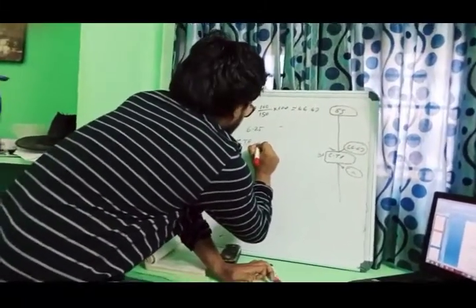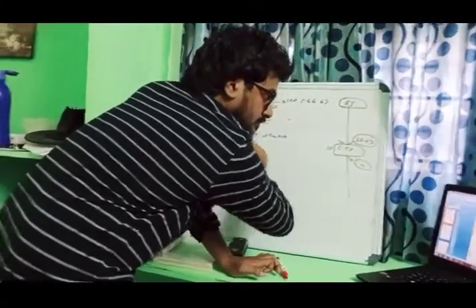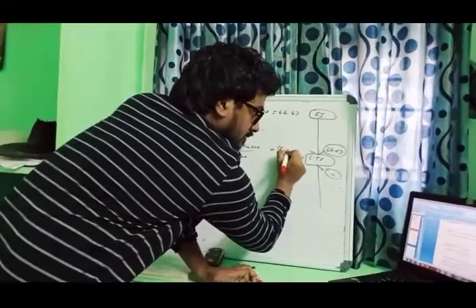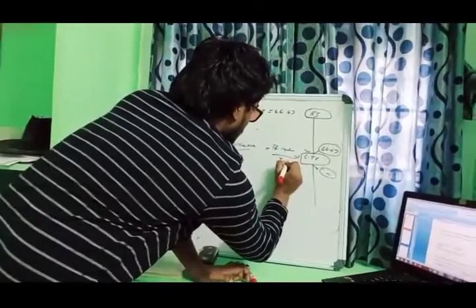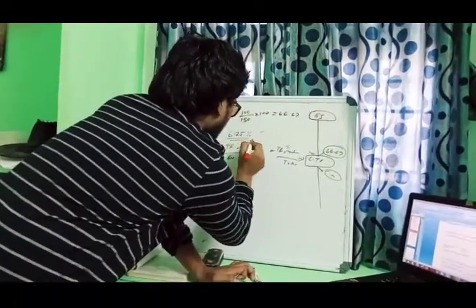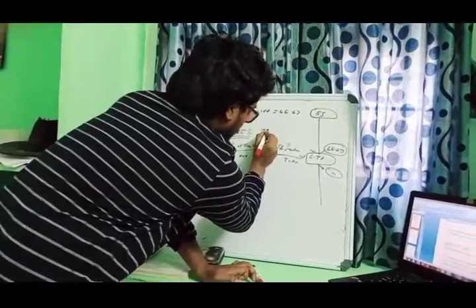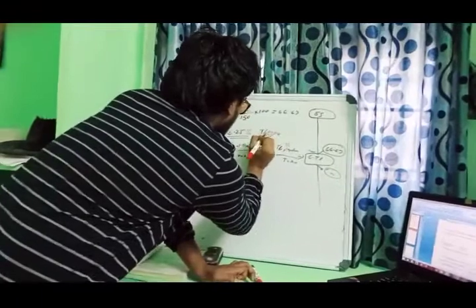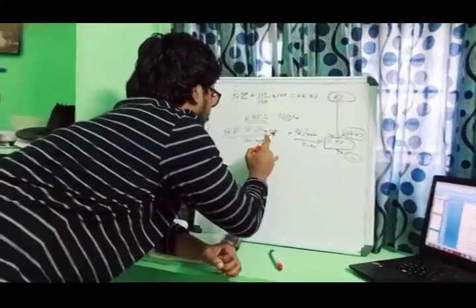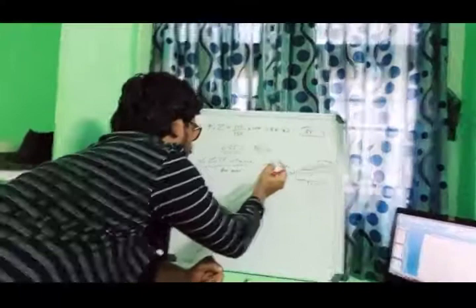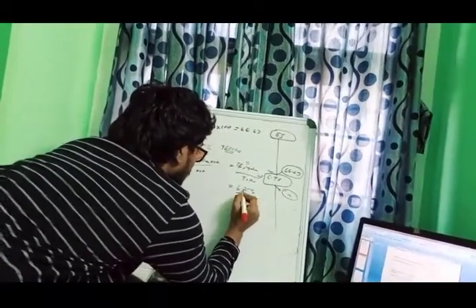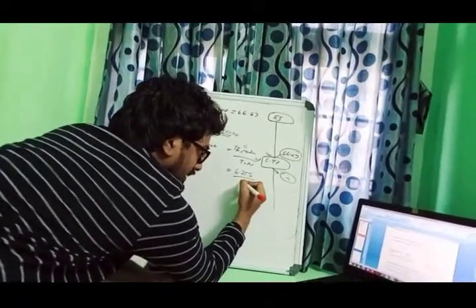Percentage impedance of the transformer at base MVA, divided by base MVA, equals the transformer's percentage impedance divided by transformer MVA. We are converting the base. This 6.25% is on the transformer's base, which is the rated value of 1600 kVA, which in MVA is 1.6.